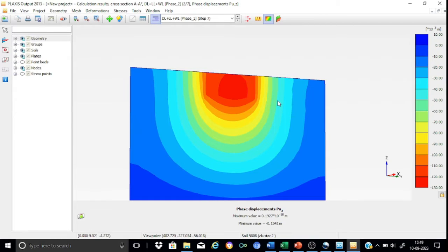It is something like the maximum displacement at around z equal to minus 4 meter. Here please note that we have almost the same displacements, because when the footing settles down, it takes some of the soil along the sides with it, because we assume in this calculation that the side loads are also active in mobilizing the resistance. That's why all these contours extend up to the top surface rather than from the bottom surface of the raft. Here we find that the maximum displacement is of the order of 124.2.